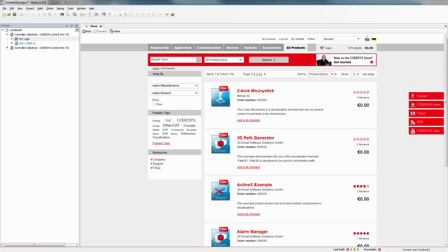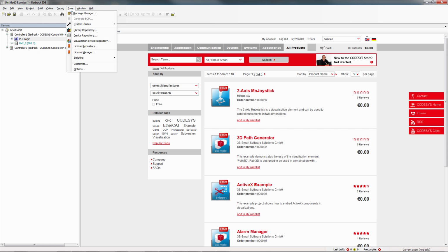All right, let's talk more about the CODESYS Store. I gave you a little preview of that earlier with the OSCAT library, but we can go into more detail here. You can get to the CODESYS Store two different ways. One is through the IDE, clicking on the little shopping cart button here, or you can go directly to store.codesys.com. If you go through the IDE, when you download, it automatically installs the package for you, so it's one less step. If you go to store.codesys.com and download the package, then you come into Tools, Package Manager, and install that package. The CODESYS Store has many features and functions available to you, more than we have time to go through now, so I'm just going to go through a quick sampling of these.